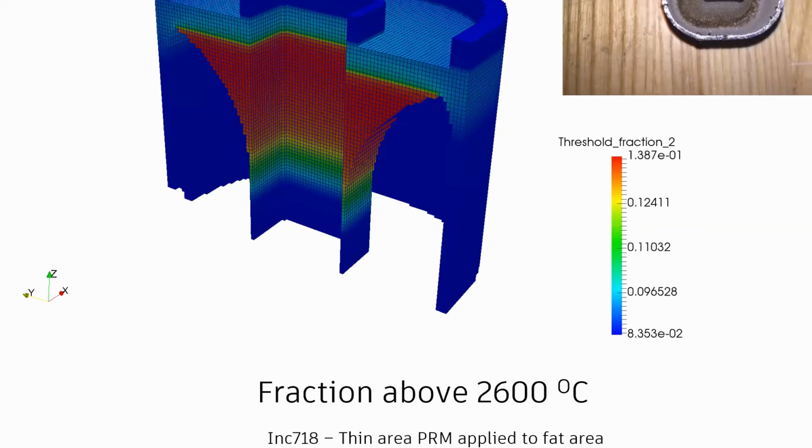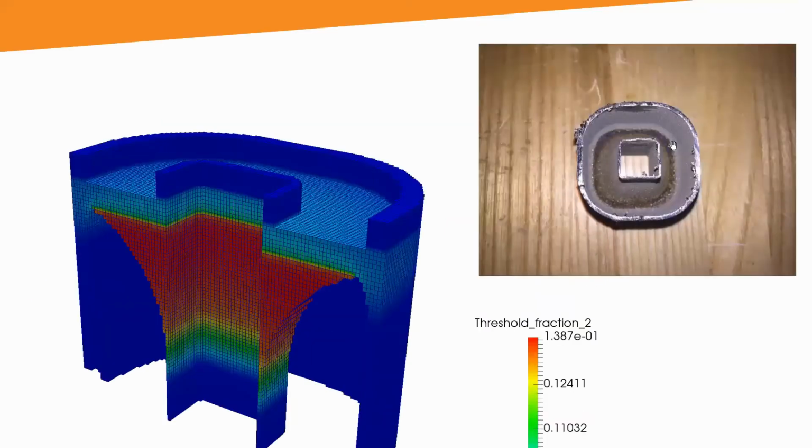You're going to end up burning the powder there. That's what we are showing you. This looks like this over here. These black marks on the real life build indicate that something has been burnt. And that generally means that you have taken that section of the part beyond its recommended operating temperature, and that part is compromised, and that is not something that you want.